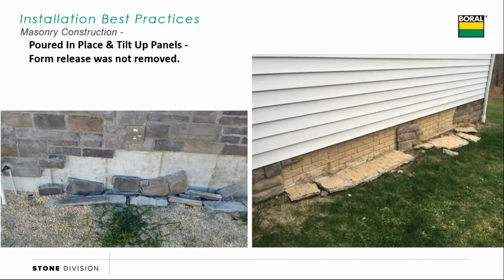I think we've all seen what it looks like when we put stone over top of a poured wall without getting that form release off. It takes a good 6 months or so, but eventually stones start sliding off the wall. It really doesn't take any pressure with your hand just to pop them right off.